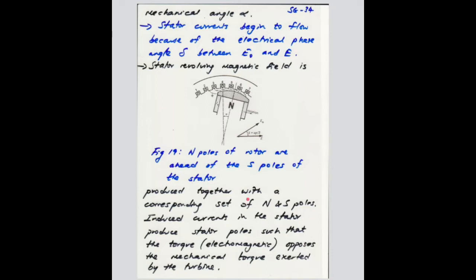That's how the electrical torque is induced on the rotor, and hence for the machine to convert mechanical power to electrical power, obviously work has to be done. So you need to oppose that electrical torque, and hence you convert the energy from mechanical to electrical.